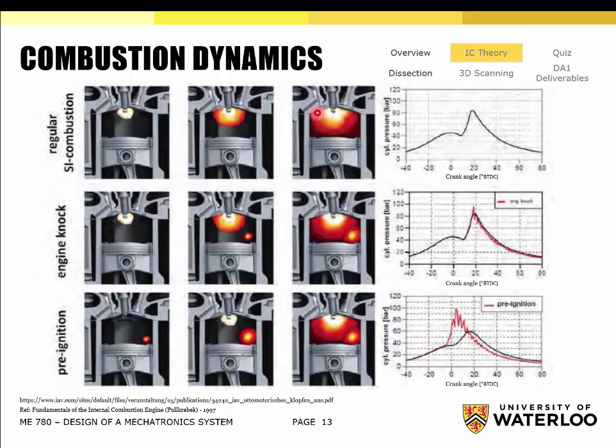What that does is when the engine is cold, that turns on, and that allows the temperature locally in that area to be hot enough to auto-ignite. So it has a spark plug equivalent to start off. Once the engine warms up, then you don't need it anymore. If you're in a warmer climate, they generally don't need it that much.